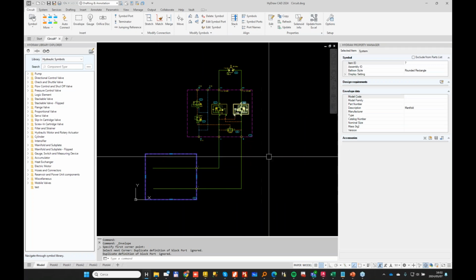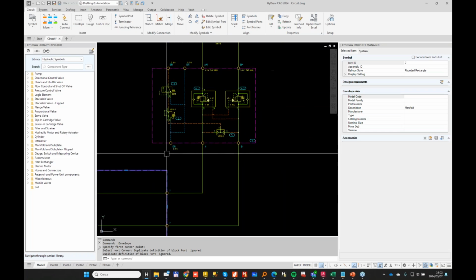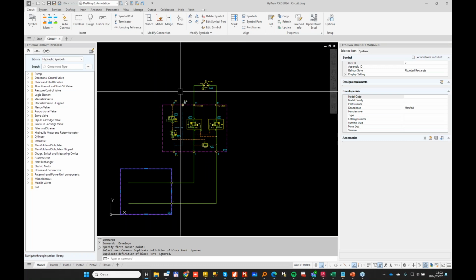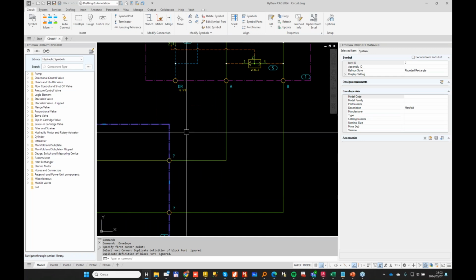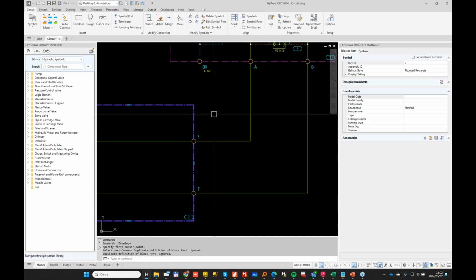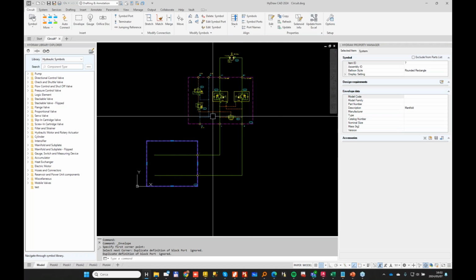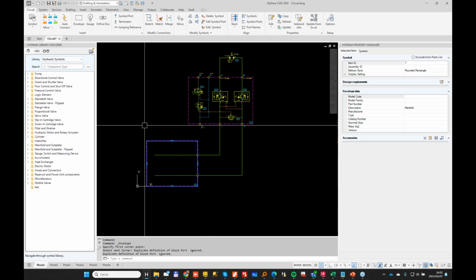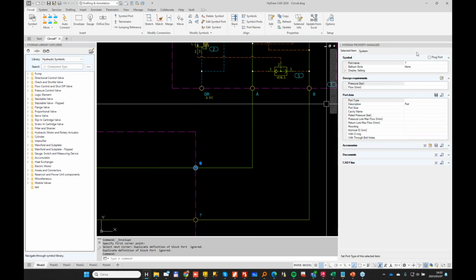This technique of creating envelopes may be used also to generate some small P&I diagrams. So when you make a connection line and break a connection line with the envelope command, remember that it will automatically create external ports. That may be interesting to conceptualize a diagram in order how the connections are made between different functional units. So that's my A port.